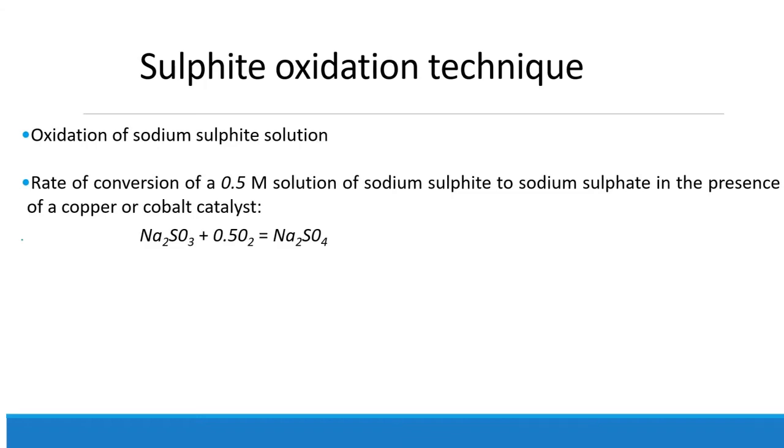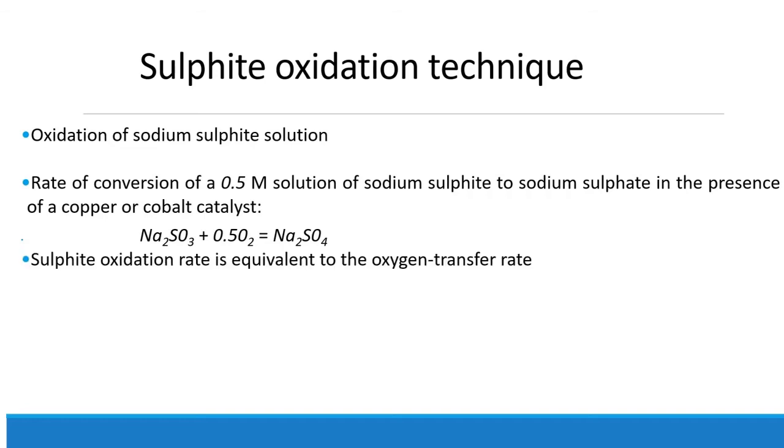The concentration of the sodium sulfite before the start of the reaction and at the end of the reaction is measured to find out the amount of sulfite oxidized. From this, we can know the amount of oxygen absorbed and consumed in the reaction. Usually, the oxygen is sparged for about 4 to 20 minutes. In this system, the chemical reaction is so fast that it is almost instantaneous.